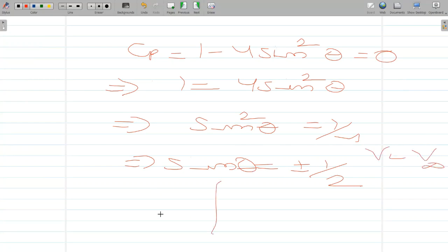Now, for right circular cylinder, from conventions of mathematics, we measure theta in this particular manner. We measure it with respect to the aft stagnation point, so theta would be taken positive counterclockwise starting from this location. But in the question they're asking us to measure with respect to the forward stagnation point and not the backward stagnation point. So first, let's characterize the location with respect to the backward stagnation point by the typical mathematical convention, and then we can convert it later on.